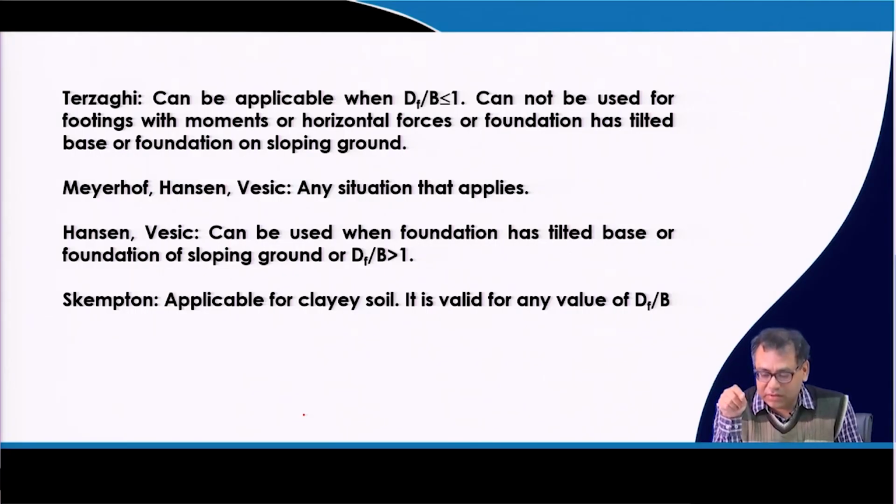You cannot use Terzaghi's bearing capacity equation for this condition. If there is a moment, you cannot use it. If there is a horizontal load, you cannot use that. If the foundation is tilted, you cannot. If the foundation is on sloping ground, you cannot. Even if the foundation is placed at a depth greater than the width of the foundation, then also you cannot use the Terzaghi's bearing capacity equation.